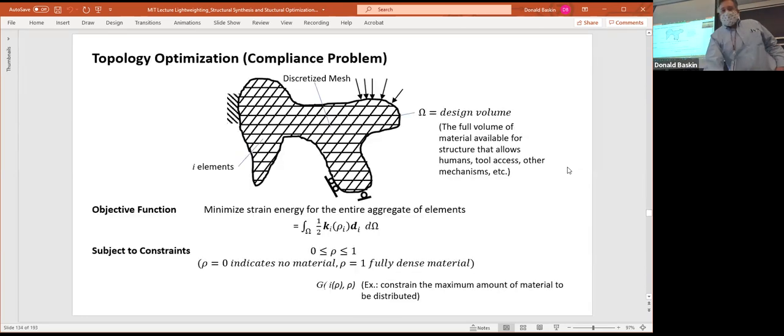And the way that they did this is they calculate out what's called the strain energy, which is 1/2 kx, so it's kind of like the area underneath the triangle. It's linear elastic, right? So the area inside the triangle is 1/2 kx. They calculate out the strain energy for each one of these elements subject to these boundary conditions. Okay, and then they add up the aggregate strain energy of this whole system. So if it had 5,000 elements, they'd have 5,000 strain energies added together. The strain energy, remember, is 1/2 kx, where the k is calculated from the density.